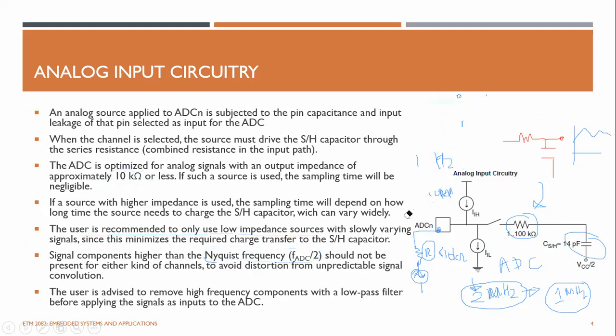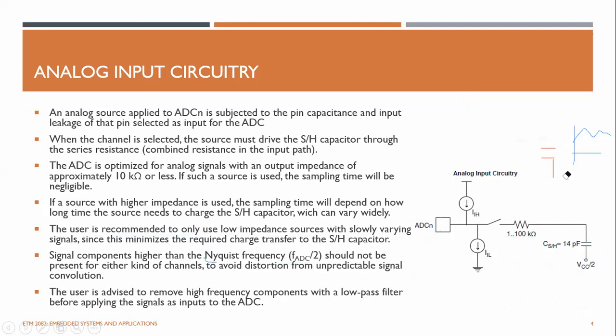So it is not only about the programming; you need to have some background about the hardware as well. When designing an embedded system or PCB layout, you need to be very careful about what you are dealing with. A pure programmer might write good code, but it will not work in the real world due to the characteristics I have mentioned, like the Nyquist theorem, high frequency components, and the charging capacitance due to the impedance of your source.